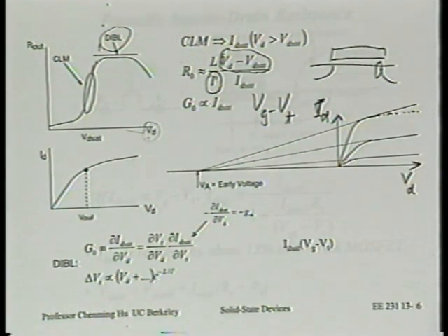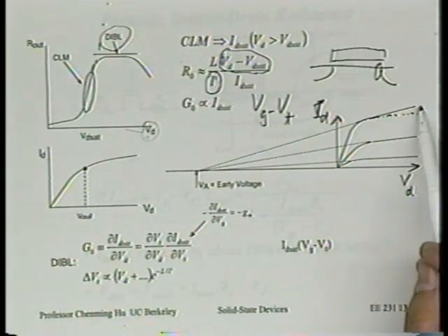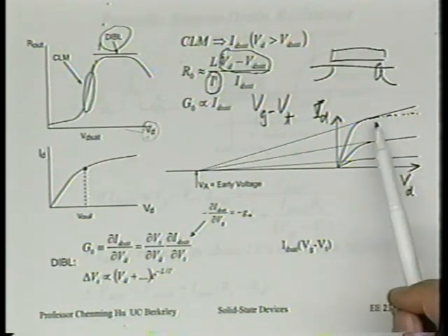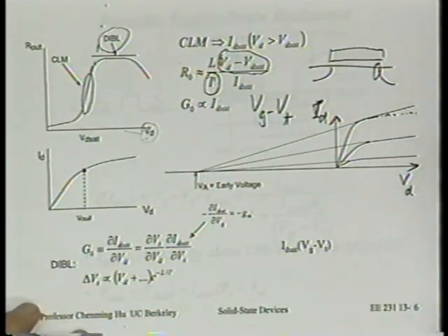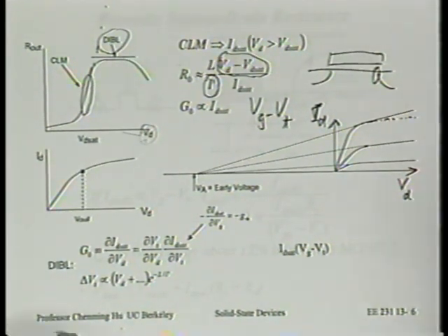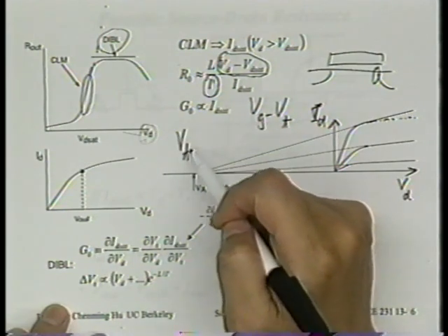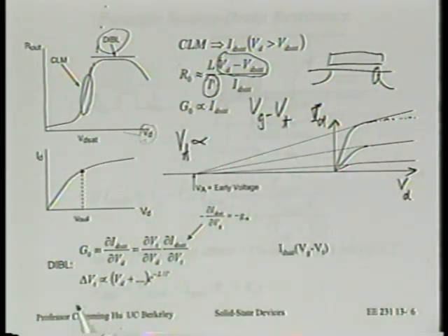And in that case, is it also reasonable that this line is linear? Because VT, to the first order, by the way, I should ask this question, test you if you remember, to the first order, what's the relationship between VT and VD? What's the relationship between VT and VD? Is VT an exponential function of VD? Someone's nodding her head. That's not right, but you get the partial credit because you're thinking of VT as an exponential function of L, channel length.